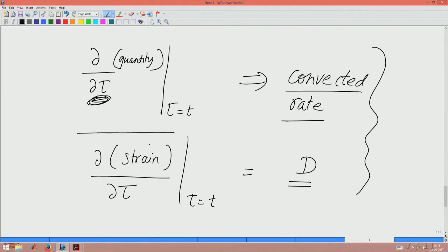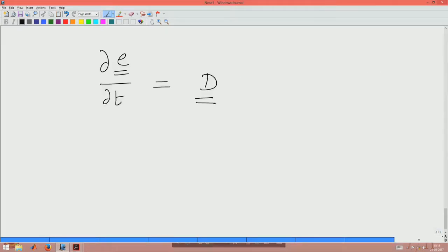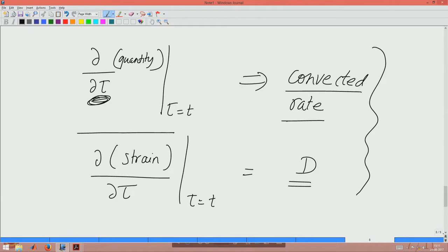We have not discussed this, but in one of the future classes we will derive it. First of all, we have to define strain, and since we need it only for more solid-like materials, we can postpone it. So, a lot of discussion in the next set of lectures. We will only worry about small deformations, material deformations which are small. In those cases we can use this relationship, where strain and strain rate are simple derivatives of each other. But in general, for a complete description we must take the convected rate of strain to get the strain rate. As a measure of deformation we should also use a strain measure which is not the small e. There are several names, like the Finger strain tensor and the Green strain tensor. Some of these we will define.